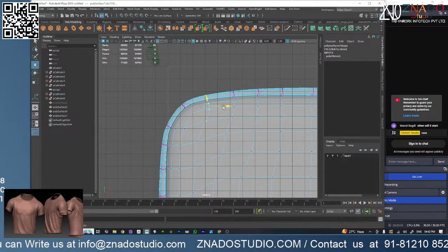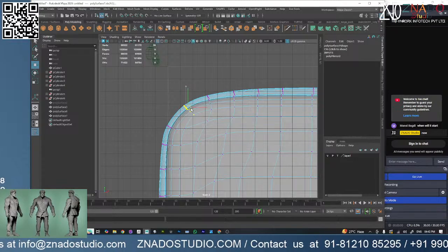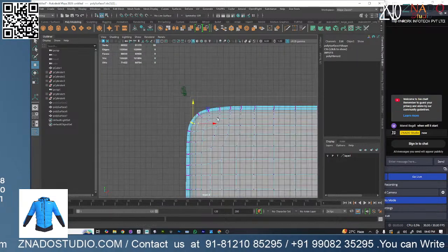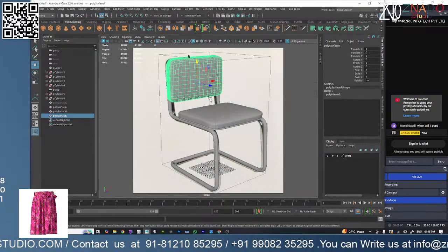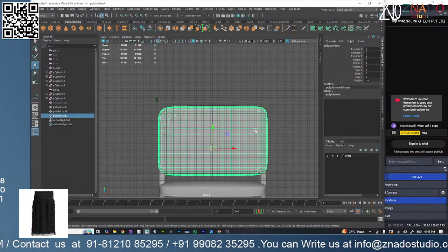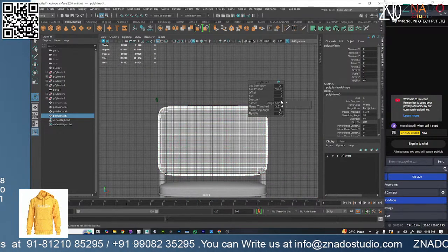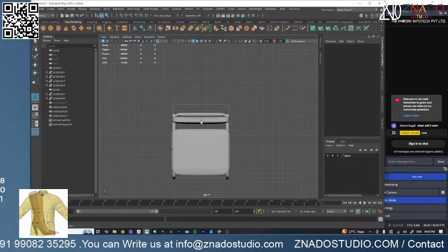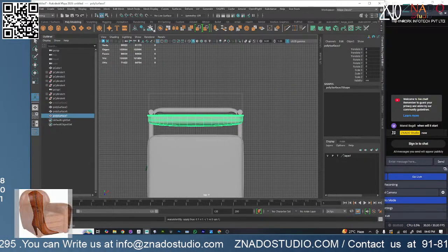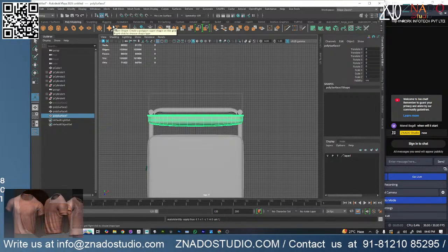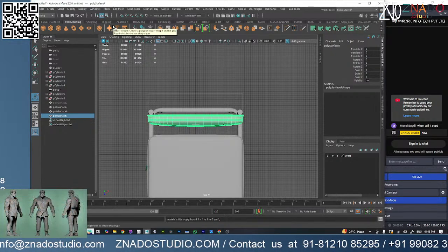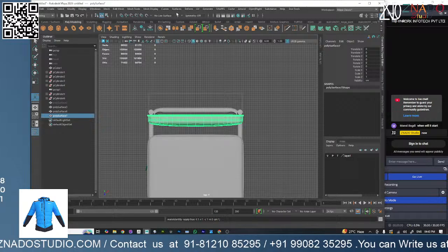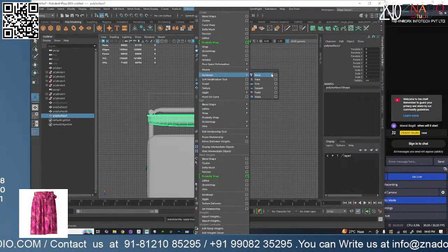but I don't want to keep this super high mesh. When I feel that the model is accurate and I don't need this additional mesh, I just delete the additional stuff. So once this is done, I'll mirror this on the other side, which is positive X. So we have both sides done, and now I want to add a deformer on top of this to make a bend. Select this object, delete history, freeze transformation for this, and then what you can do is deformer, non-linear and bend.